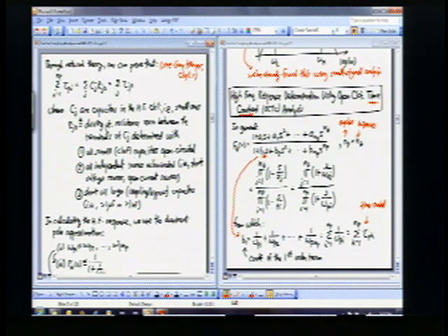Small capacitors means on the order of 1 nanofarad or less. That's a small capacitor. If you have a capacitor like that, you open circuit that in this calculation. If you have a capacitor that's large, like greater than a microfarad or say greater than 1 nanofarad, that should be short circuited in this analysis. And then finally, all independent sources, you short the voltage sources, you open the current sources. So you're zeroing out those independent sources, which is the same thing you've been doing for the midband analysis. All right, so what you're going to end up doing is calculating a time constant like this.